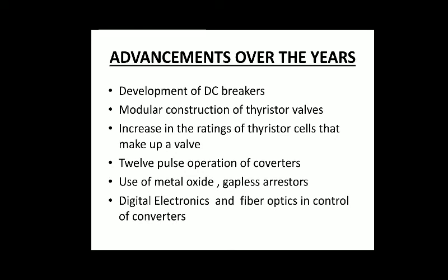But with the advancements over the years, the disadvantages have been minimized. The advancements are the development of DC breakers, modular construction of thyristor valves, increase in the ratings of thyristor cells that make up a valve, 12 pulse operation of converters, use of metal oxide arresters, digital electronics, and fiber optics in control of converters.